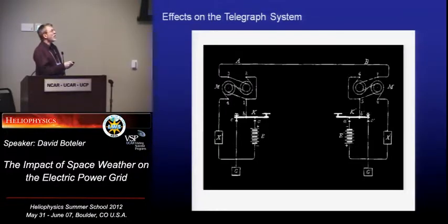But what they found during the storm was that neither operator was doing anything, yet the signaling apparatus was operating, and that's because of induced voltages on the lines. And so they were getting a lot of chattering of the equipment.